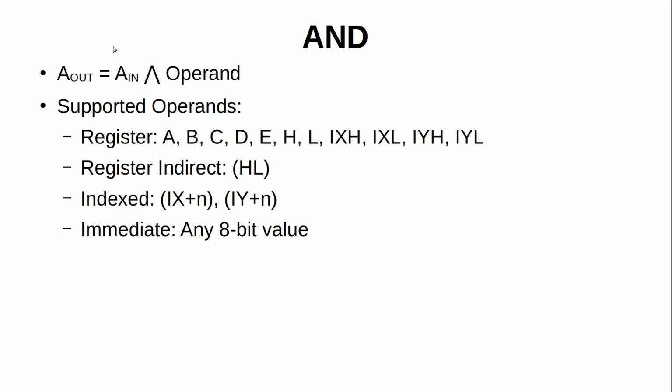Otherwise, AND is mainly used to clear a set of bits in the accumulator, often with an immediate bit mask. Each bit that is clear in the value will be cleared in A, while the set bits are unaffected. A good example is again with decimal numbers, except we can use an AND 0F to clear out the upper nibble and just get the value of the decimal digit represented by a numerical character code.